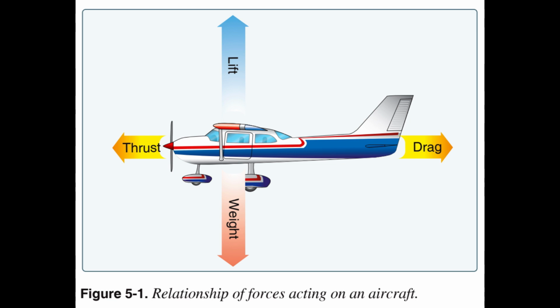Therefore, in steady flight, 1. The sum of all upward components of forces, not just lift, equals the sum of all downward components of forces, not just weight. 2. The sum of all forward components of forces, not just thrust, equals the sum of all backward components of forces, not just drag.